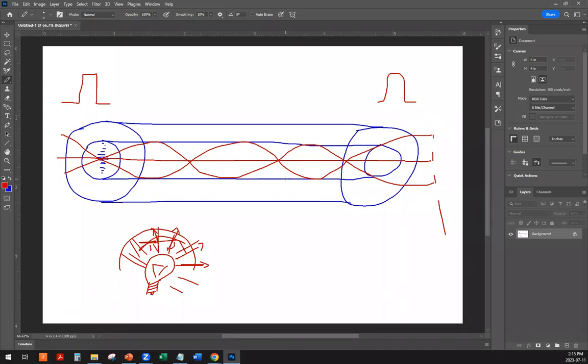an IDF, which stands for Intermediate Distribution Frame, which is a communications closet with a bunch of patch panels and switches. And it will also have a media converter that would convert everything into the fiber optic signal. So the intermediate distribution frame is going to be strategically placed in whatever building to accommodate the distance of no more than 300 feet end to end, so the copper wiring can be distributed to the cash registers, to the phones, to PCs, wireless access points, and whatnot.